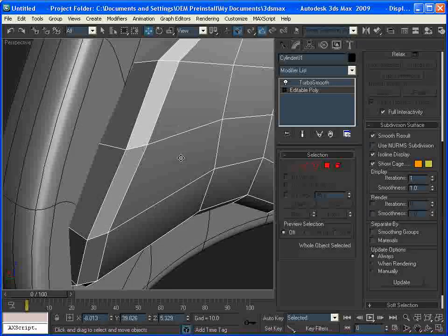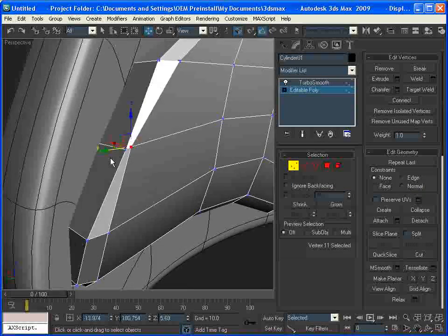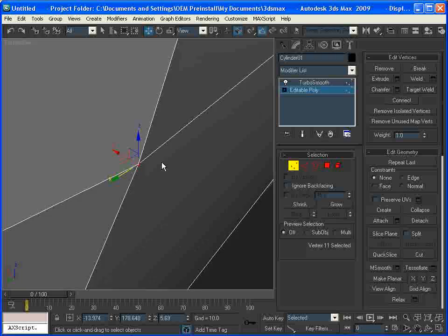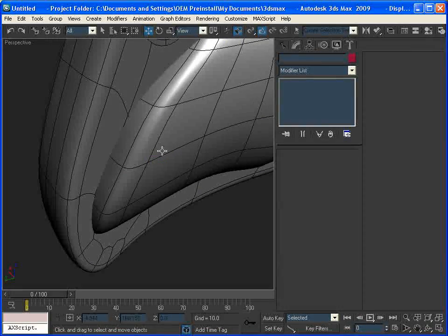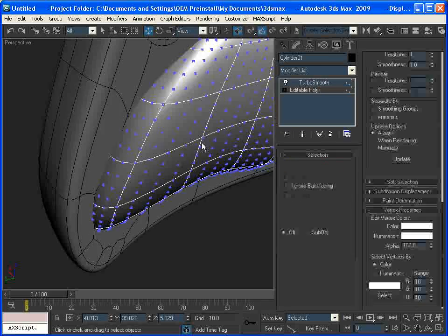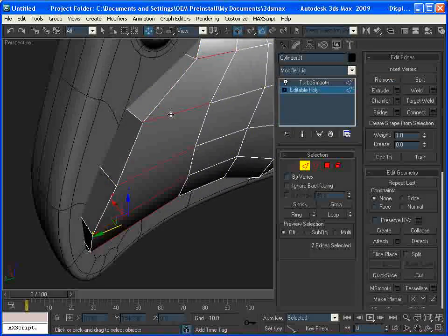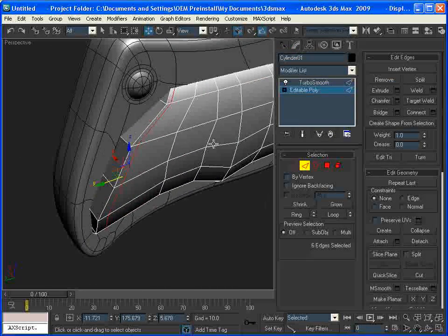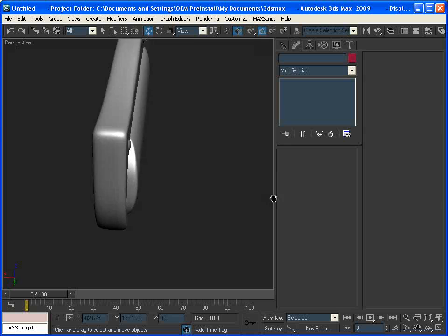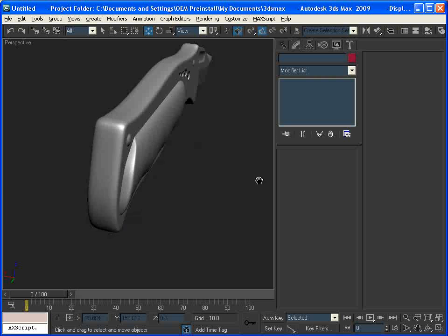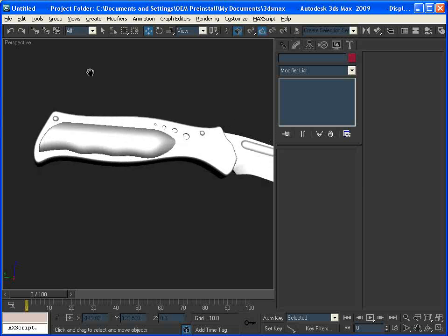We can't easily move this chamfer without messing things up. It doesn't preserve the original line, it alters it. So the benefit of using a supporting edge that we just add with a connection is that later on, if we decide we don't want it, we can just select it again, boom, it's gone. And we still got that original curve there. So that's why it's almost always better to just use a supporting edge rather than a chamfer.